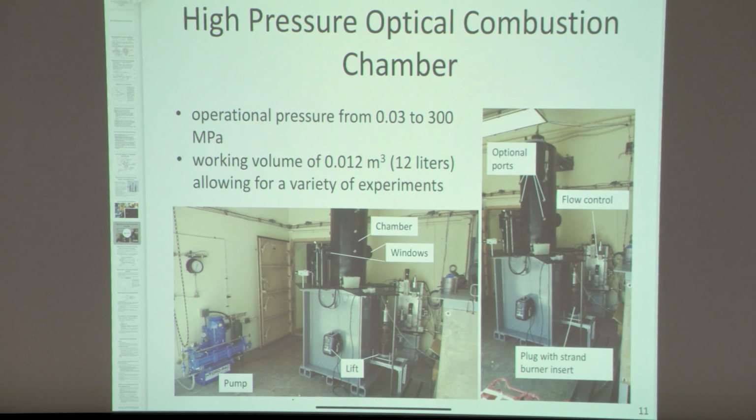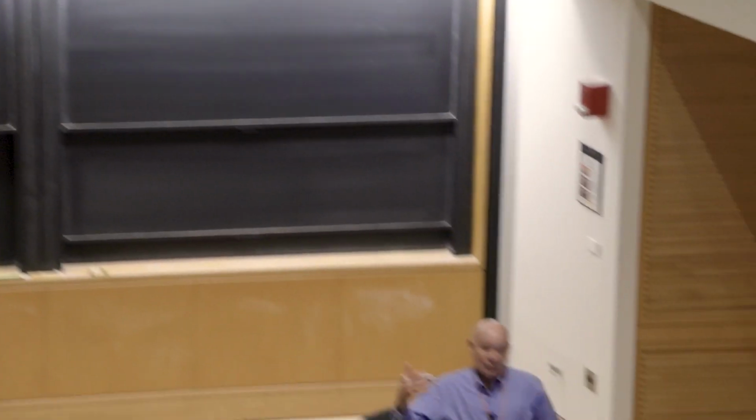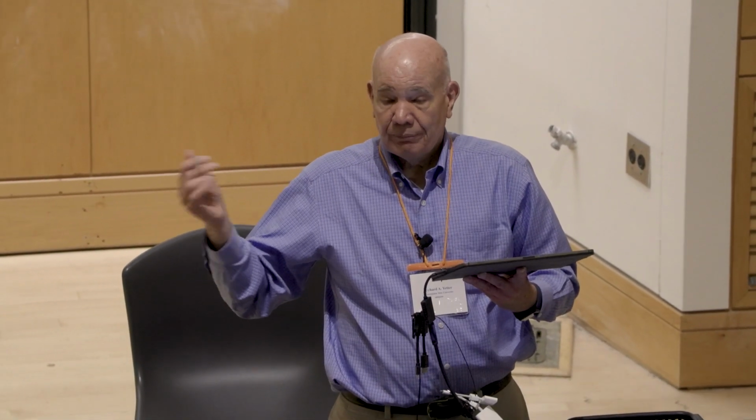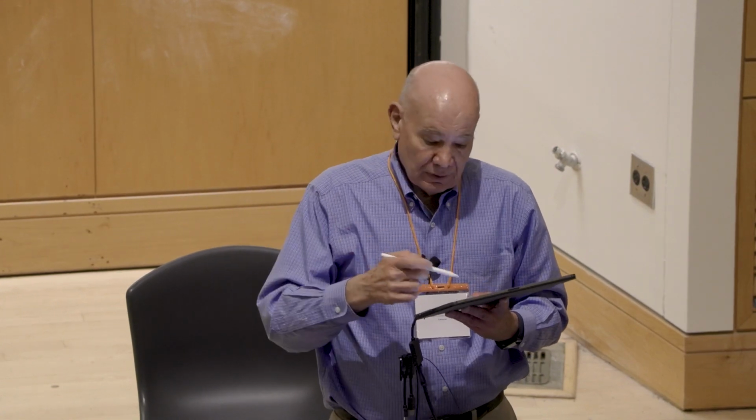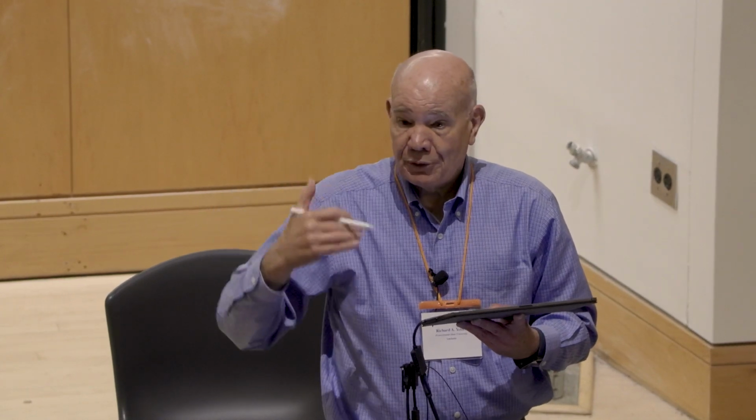This chamber goes to 50,000 PSI with an optical window. The optical window is about 4 inches thick. And the reason we were interested in making this device is for two reasons. If I'm looking at building a rocket motor, typically the highest pressure you deal with in standard rocket motors is, and I'll show you why later, about 2,000 PSI. The standard reference pressure is 1,000 PSI, but you won't find many motors today going over 2,000. Okay? But if I'm looking at a gun propellant, then those pressures go up to about 100,000 PSI. And so this device gives us a measurement getting close to that value, to be able to observe how it burns.